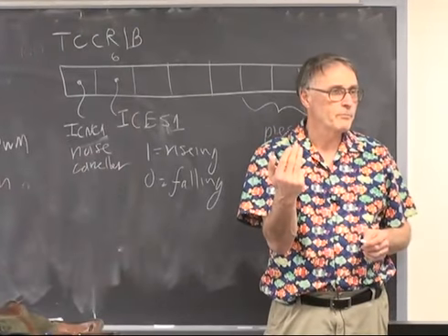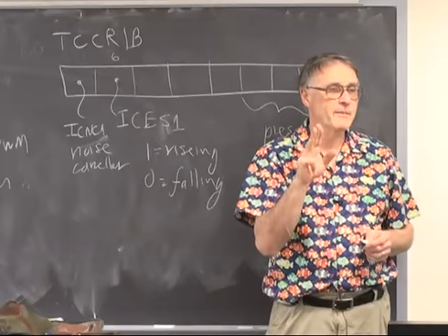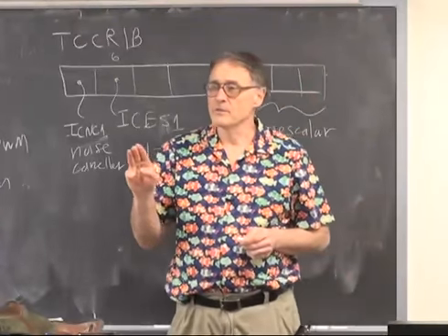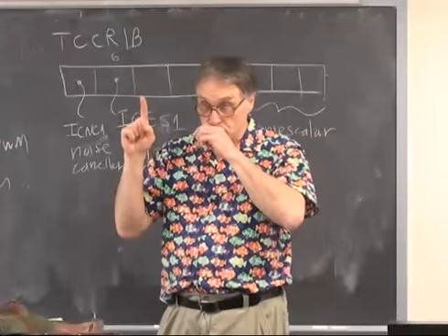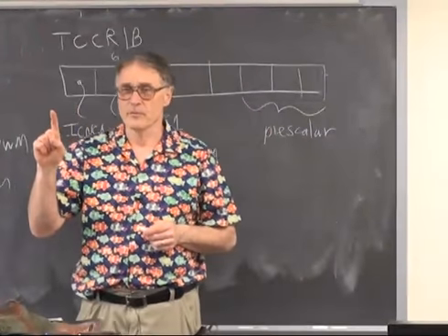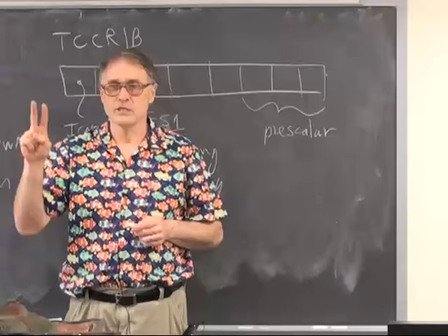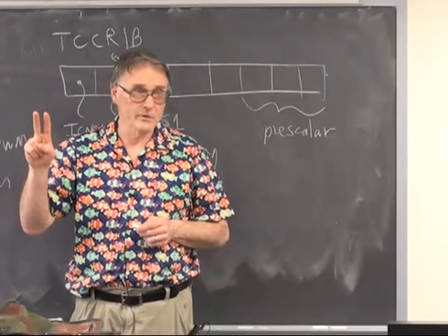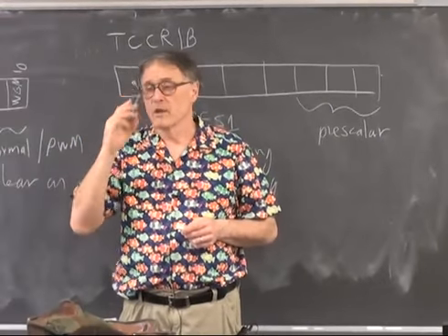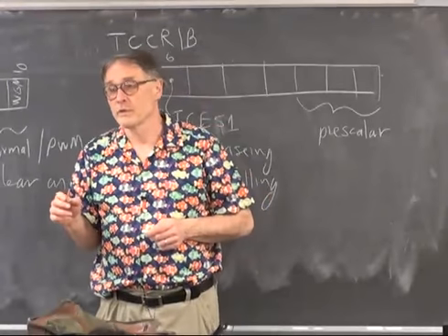And the code I put online does that measurement 2 different ways. It uses the input capture register directly with an interrupt, which is the preferred method, and then it uses a really cheesy low accuracy method, which polls the timer in real time.